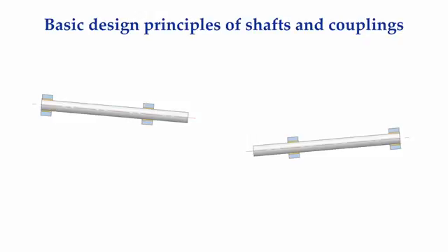For this discussion, let's say that we happen to have 2 shafts in this particular misalignment condition. We want to somehow link these 2 shafts together, right? To connect these 2 shafts together, we are going to install a link between them. This link is going to be called a coupling. For this to work, there needs to be 2 flexing points at each end of the coupling, right? What you need to understand is that when rotation starts, the shaft on the right, the coupling, and the shaft on the left are going to rotate on 3 different center lines of rotation.